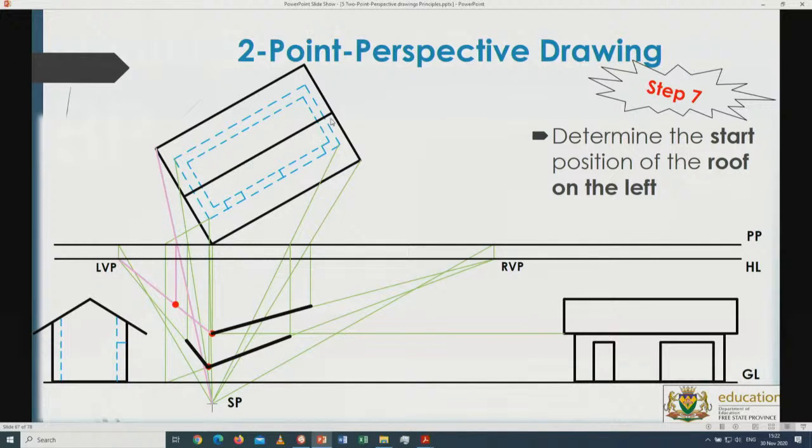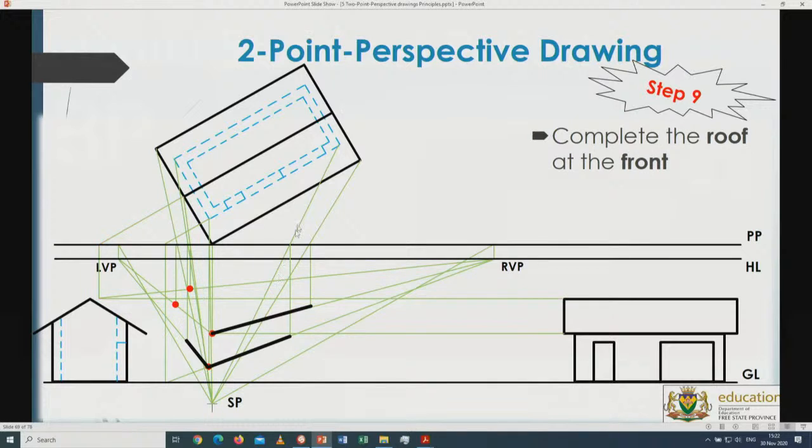Alright, now if I have to do the top of the roof, I think that's the next step. Yes, the top of the roof is going to the picture plane. It goes downwards till I reach the height. Remember, you don't need to draw the line all the way over from this side to there, because the height is also there, so I could have used that short little distance over there as well. This will disappear to the right, so somewhere on that line is my roof. Where do I find it? Picture plane downwards, find it over there. This point over here, where do I end with the roof? Standpoint, intersect with the picture plane. Sorry, there we go. Standpoint, intersect with the picture plane, and find it on that line over there. Alright, so there we go with the roof.